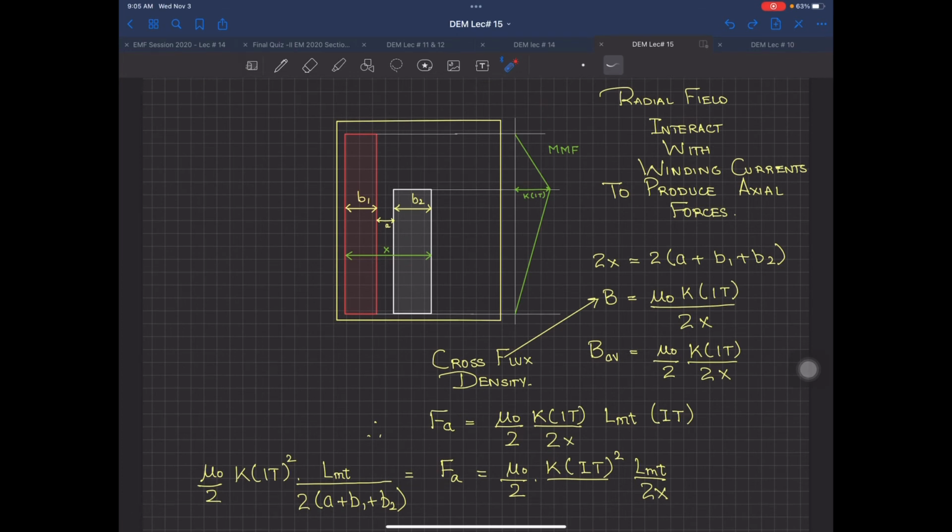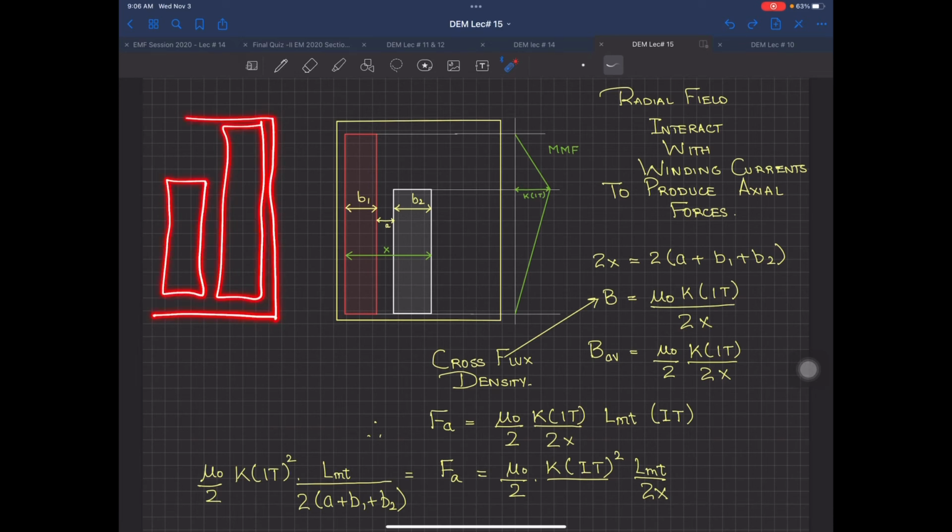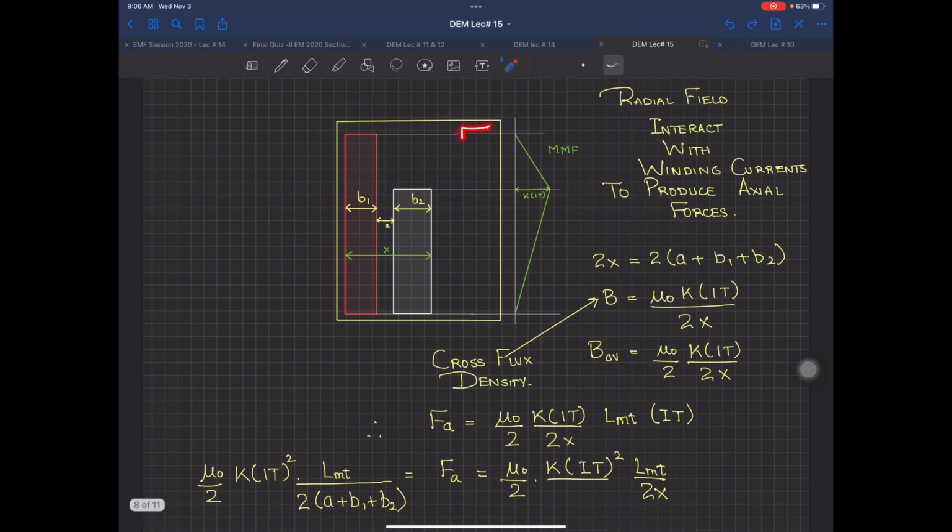You have B1 as the thickness of the LT winding or low voltage. B2 is the thickness of the other one. And certainly when you are going to complete this transformer, this is the central limb. So there will be a low voltage winding on this side, and then certainly there will be a high voltage on this side. So this distance is X, then this distance over here is also X. And the other winding which will be drawn in the same window over here like this.